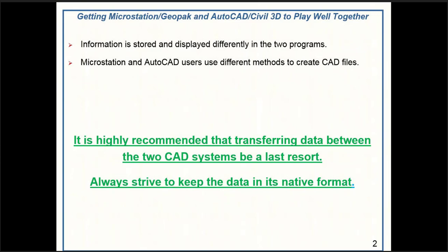If you're trying to import or export Civil 3D data, or some of us know this as AEC object data, like architectural, electrical, or construction, objects like alignments, surfaces, and profiles, or other intelligent objects, you should look into the option of importing or exporting via XML or just recreating the objects altogether. And I'll demonstrate how to export your data to LandXML later on in the session.